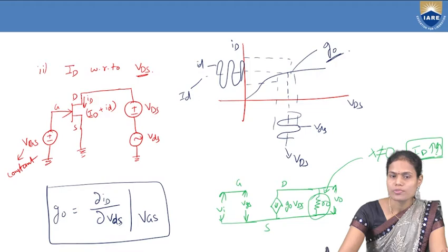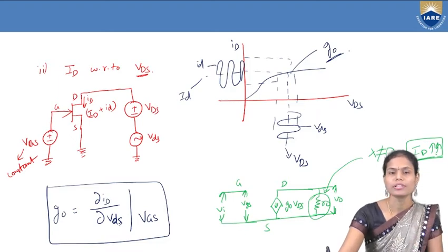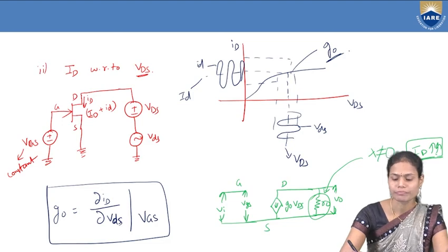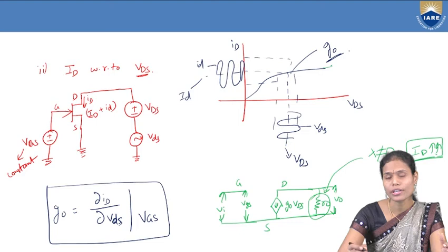And if we observe here, in both the cases, we didn't consider any capacitor effects. Why? Because at low frequencies, or for low frequency AC signals, the reactance of the capacitor is very high. So once the reactance of the capacitor is very high, it acts like a high resistance path, so it will not allow the signals here. So we cannot consider the effect of that one here. That is nothing but it will not be able to allow the AC signals.